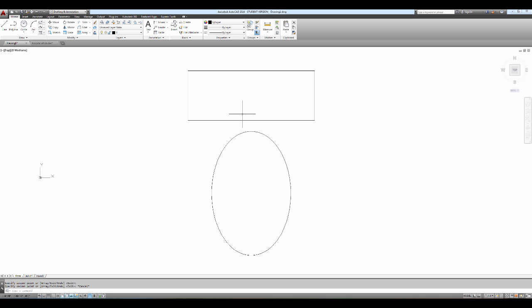So say we did this symbol and it's fine for the initial drawing, but they wanted more detail on it and said, could you round the edges on the toilet, and could you put a handle on there, and could you make it look a little bit better, basically. So let's do that. I'll do a fillet with a small radius, and we'll fillet the tank all the way around so it'll have nice curved edges.